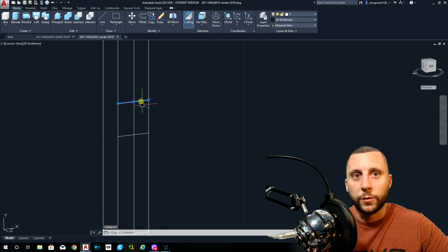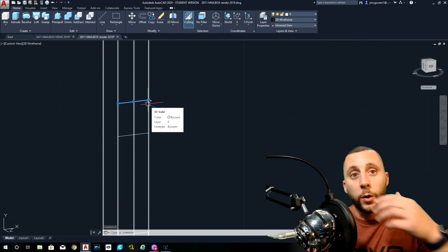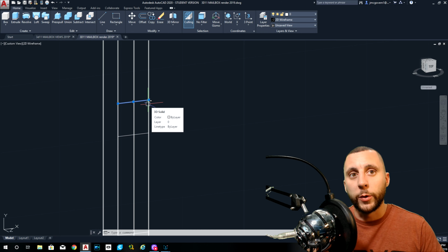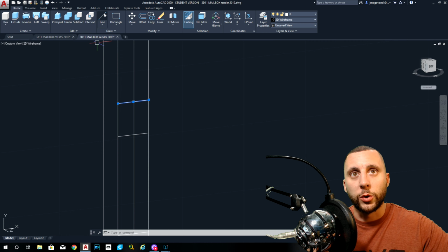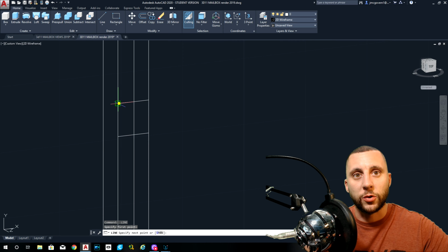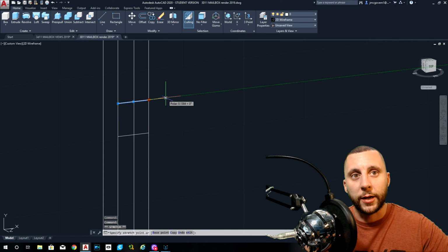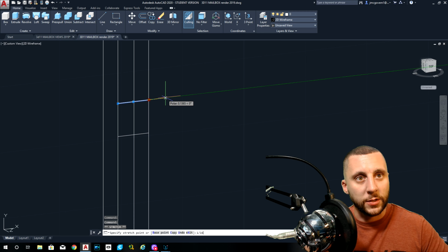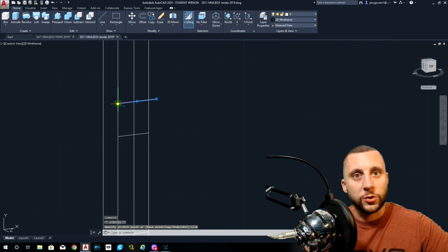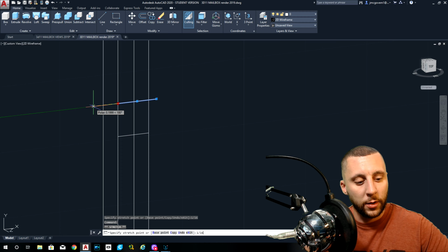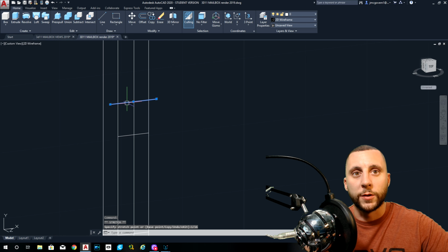You've got this line here that is 1/4 inch long. 1/4 is the same thing as 2/8, but we need this to be 3/8. So you can't just draw a 1/16 this way and a 1/16 that way, hoping that adding 2/16 would get you to 3/8. You really should take this line and stretch it by 1/16, and then stretch this side by 1/16. That way you're still manipulating just one single line.